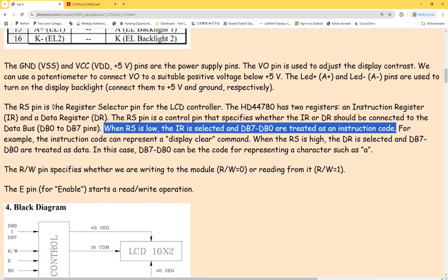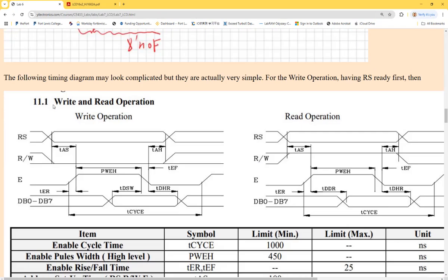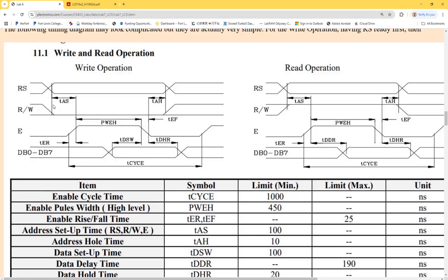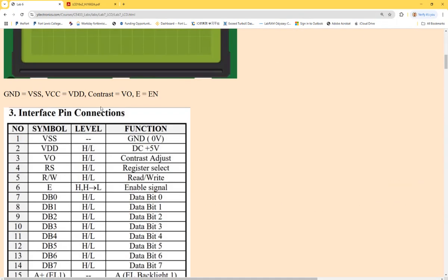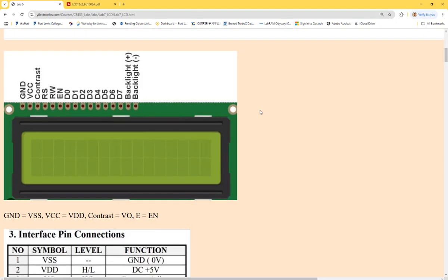It's a physical pin. Okay, it's going to be a 0. Since we don't need to change it, in that case, you can directly just ground it. So when you are making the connections, just directly ground RW. We'll be fine. You're always writing to it.